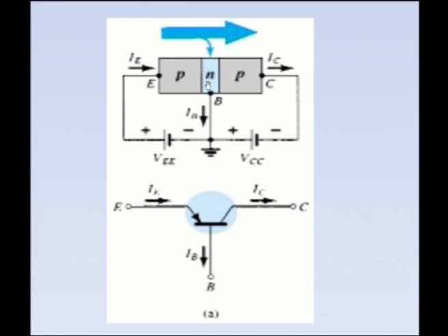We know that if both the junctions are forward biased, the current is very high, and if both the junctions are reverse biased, the current is 0, apart from a low microamp or nanoamp range of current due to the minority carriers. So, we are going for forward biasing the input junction and reverse biasing the output junction. This is what we have to remember for drawing the circuit diagram.